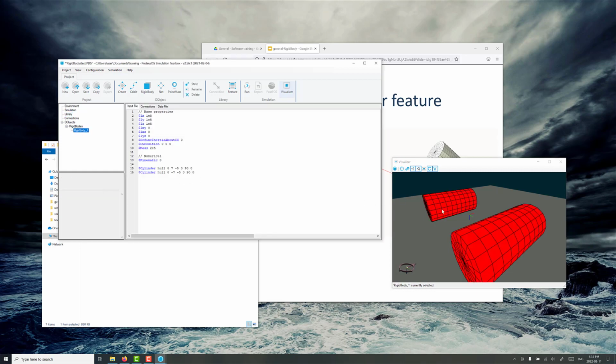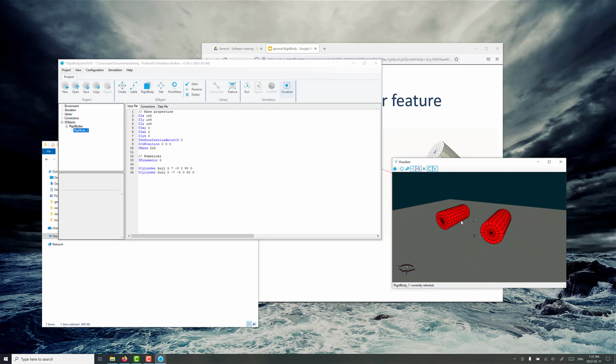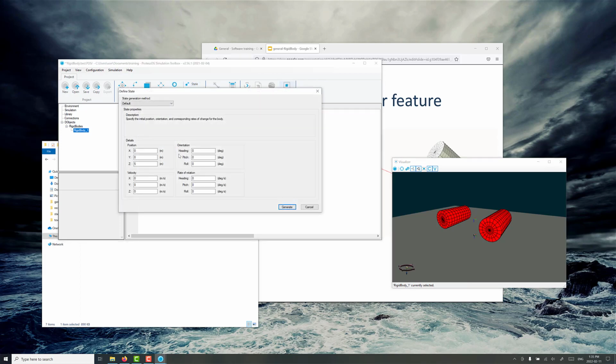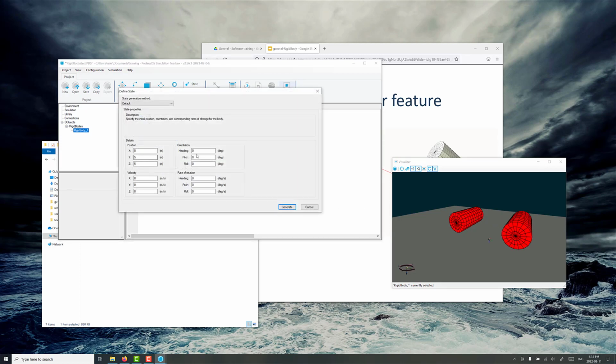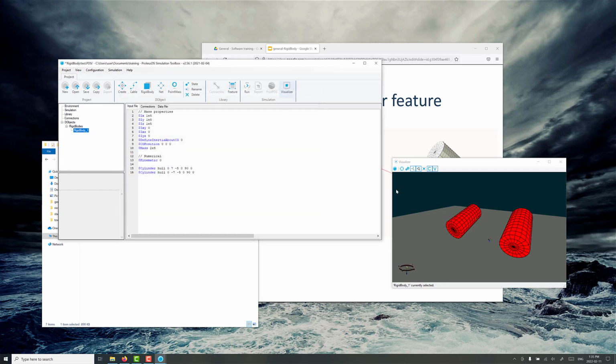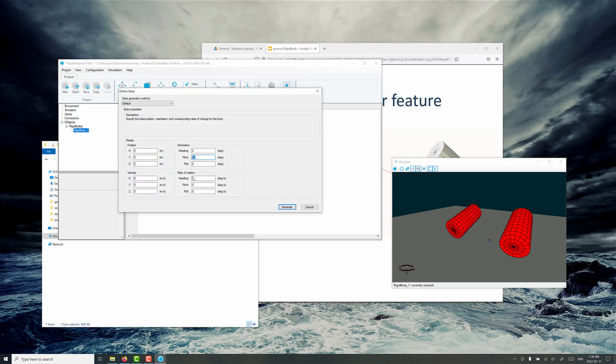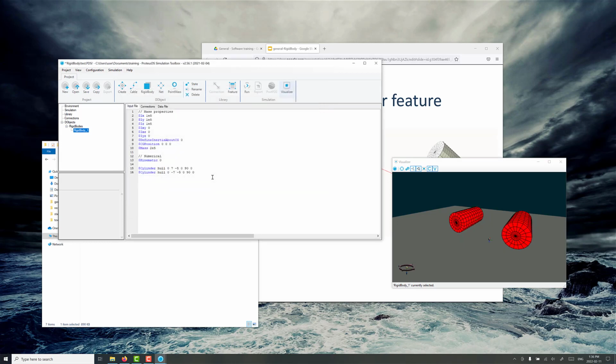And again, remember, this is one rigid body system. So if we change the state, even though these don't physically look connected, they are part of the one individual rigid body system. If we go to the state of the rigid body and move them offset in Y, it moves them together as a system. If we give the whole system a pitch of, say, 15 degrees as its starting orientation, they all move together as a single system. So don't confuse the rigid body orientation and the feature frame orientations. The features are always fixed with respect to the rigid body.